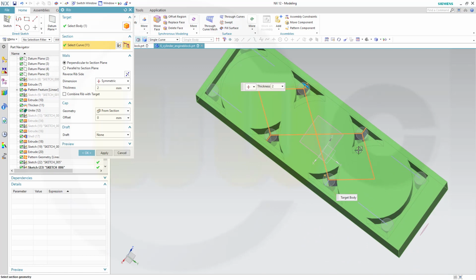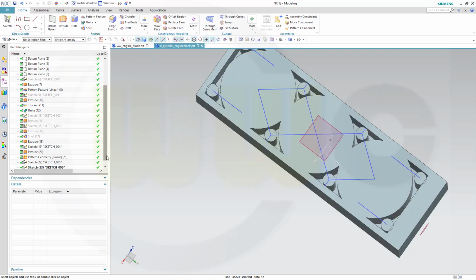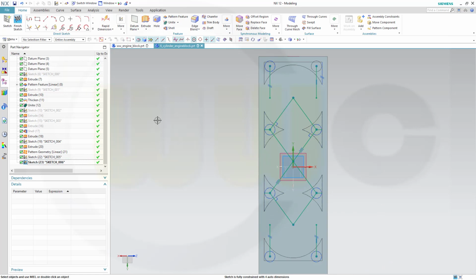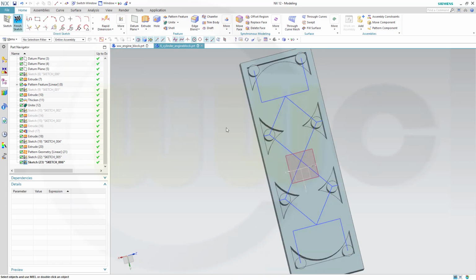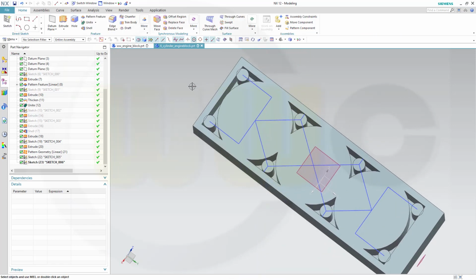And you might notice as soon as you make sort of a corner, it will not extend. So I could go right this way. So let's cancel this out and change the sketch once more. Add some lines. So go from this one over there to this one. And right there. So it should not extend. So it could go for feature.